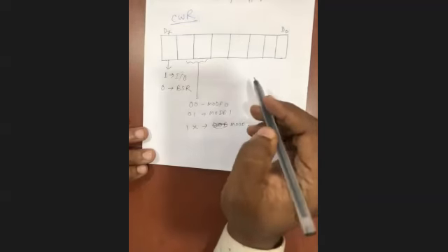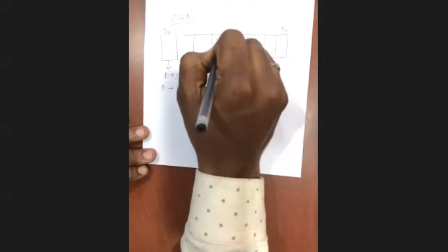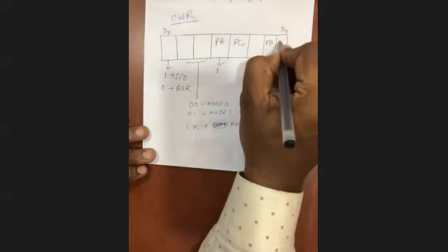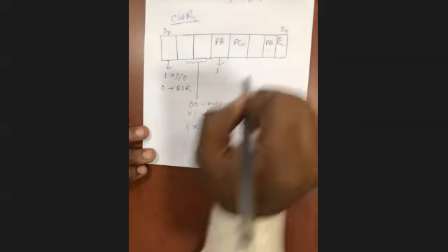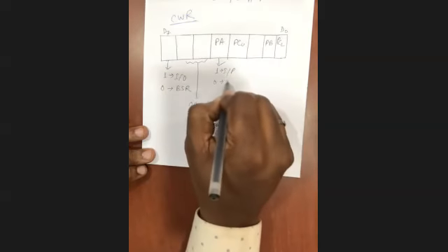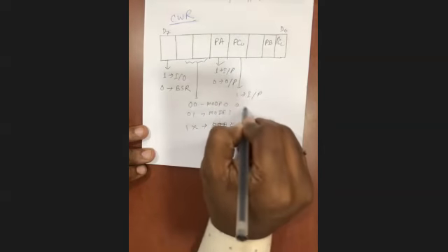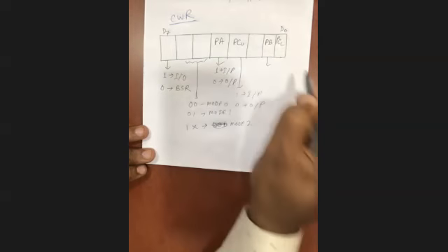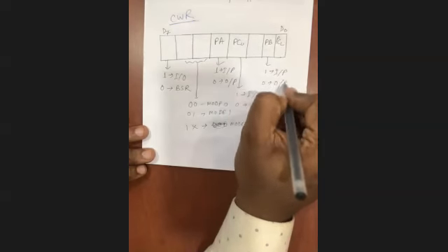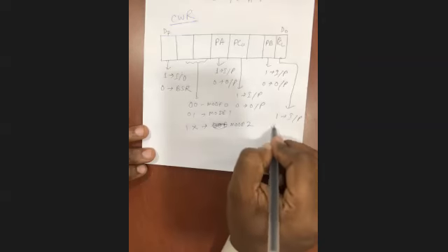If I'm talking about mode 0, then these bits are for PA, PC upper, PB, and PC lower. If the bit is 1, then it's input. If 0, then it's output. Similarly, 1 for input, 0 for output, for each of them, and PC lower is likewise 1 for input, 0 for output.